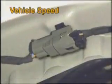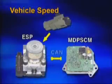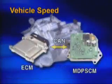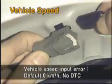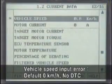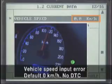In case of the vehicle equipped with ABS, the vehicle speed of MDPS is the value of the right wheel speed sensor received from the engine ECM via CAN. With manual transaxle spec, the vehicle speed is received from the engine ECM via CAN. If the speed detecting sensor, such as the right wheel speed sensor or vehicle speed sensor, is electrically faulty, then the MDPS CM recognizes the vehicle speed as 0 km per hour and there is no error code.